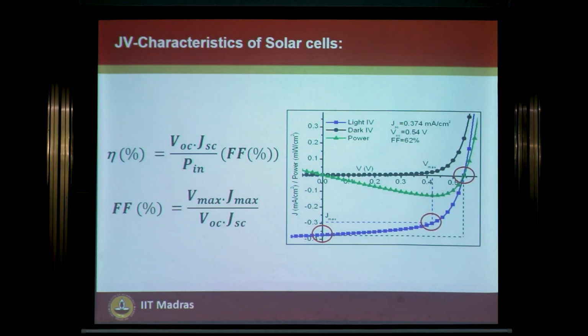So with this, there are three important parameters in solar cells one has to look into. One is the JSC, another is the VOC, and another is the fill factor, which basically tells how ideal your diode, the photodiode, is. Out of these three, in the coming slide, I'll be explaining one of them, the VOC, the open circuit voltage: how you can reduce some of the losses compared to the band gap of the semiconductor, and attain maximum VOC from the solar cells.